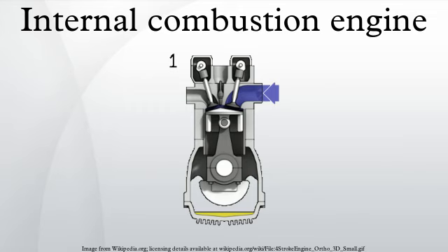Engine cycle. Two-stroke. This system manages to pack 1 power stroke into every 2 strokes of the piston. This is achieved by exhausting and recharging the cylinder simultaneously. The steps involved here are: intake and exhaust occur at bottom dead center. Some form of pressure is needed, either crankcase compression or supercharging. Compression stroke, fuel-air mix is compressed and ignited. In case of diesel, air is compressed, fuel is injected and self-ignited. Power stroke, piston is pushed downward by the hot exhaust gases.